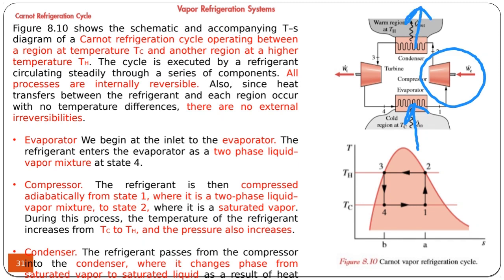You normally remove heat from the cold temperature inside the refrigerator and it's transferred into the kitchen. So if you hold the back of the refrigerator, you will see that it's warm because heat is transferred to the kitchen there. It's absorbed from the inside, from the food, plus the work from the compressor, and the sum of the two energies is transferred to the outside from the condenser.